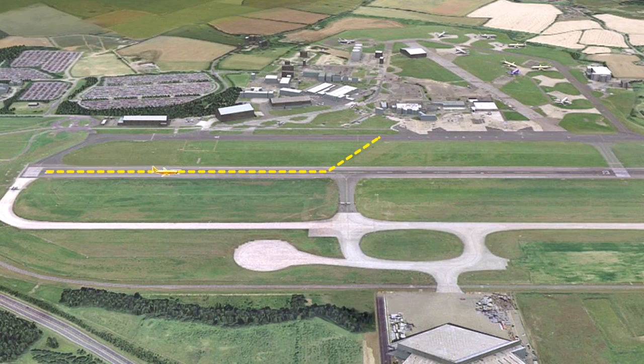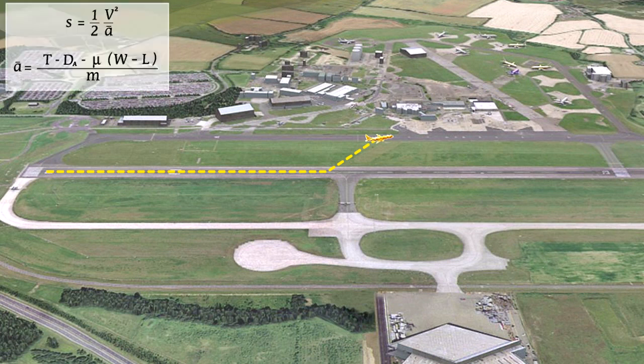The first of the factors that affect the takeoff is the effect of mass. Increasing mass has 4 significant effects on the takeoff, all of which can be observed in the formula for the takeoff distance. The first is that a greater amount of mass for a given applied force will reduce the acceleration that the aeroplane can achieve.